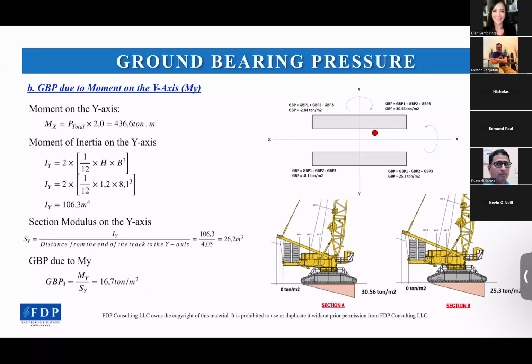So it will correlate together between your crane and your soil, because if you have an onshore operation, the critical point is your soil support. And if your operation is offshore, the critical point will be the waves and the trim of the vessel. So I encourage your team to contact geotech people to provide a detailed report for your operation, especially if you have a heavy lifting operation.